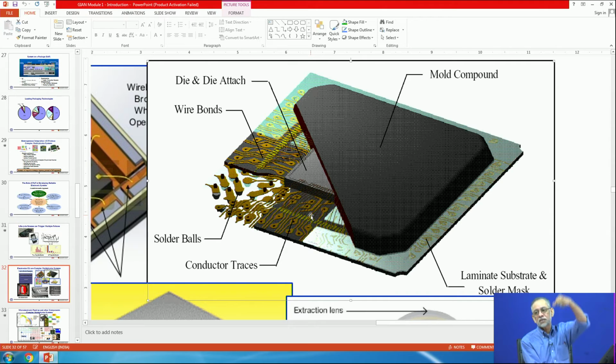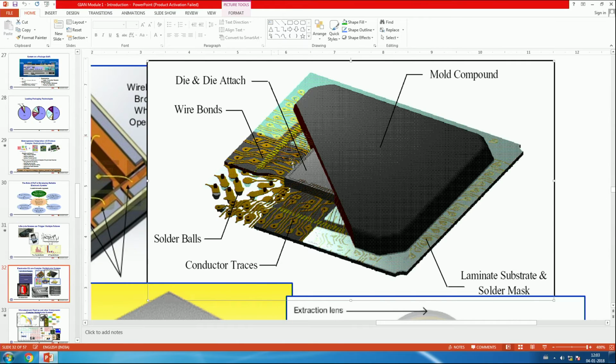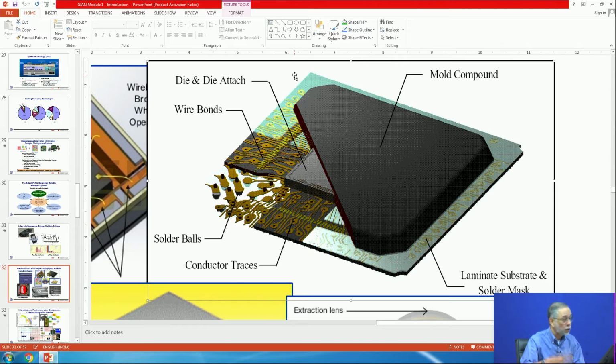So now the wire bond is seeing fatigue loading, and eventually the bond pad where it's bonded will fail. What makes it worse is this is not hermetic, meaning moisture is getting into it. All polymers absorb moisture, and that moisture eventually ends up accumulating in those regions, and so the moisture causes corrosion on the bond pad.